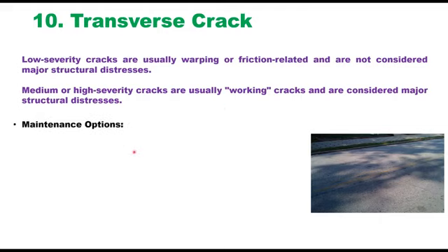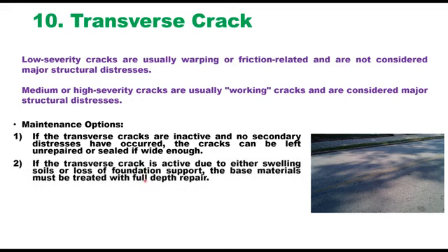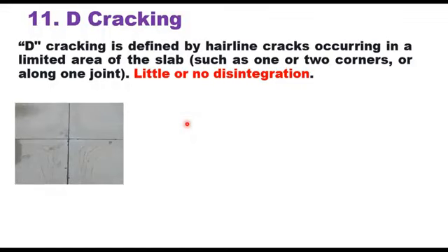The maintenance options which are available: if the transverse cracks are inactive and no secondary distresses have occurred, the cracks can be left unrepaired or sealed if they are wide enough. If the transverse cracks are active due to either swelling soils or loss of foundation support, then base materials must be treated with full depth repair.